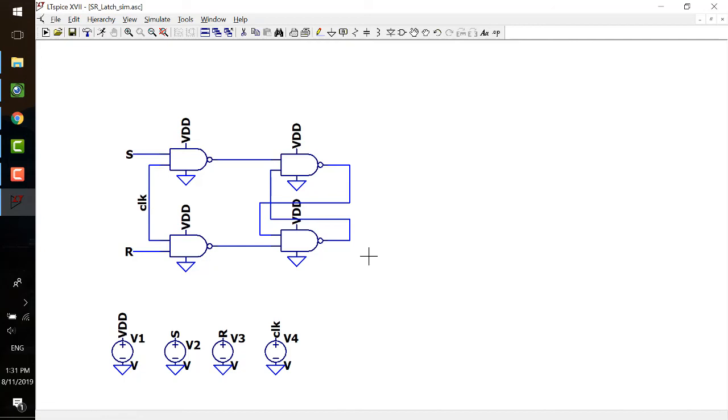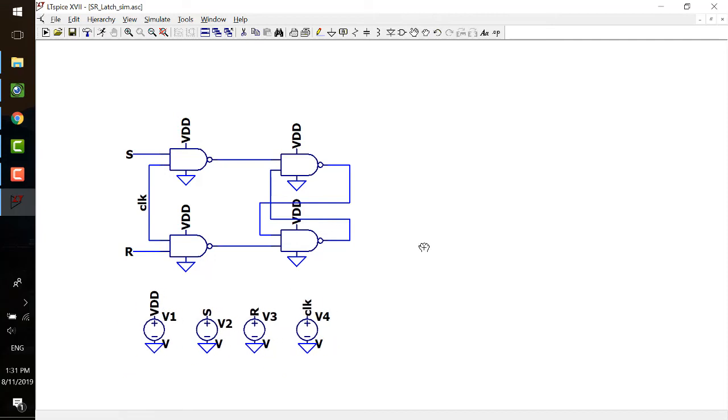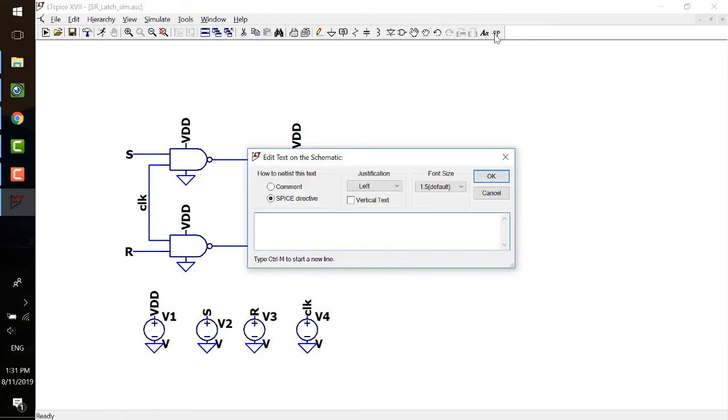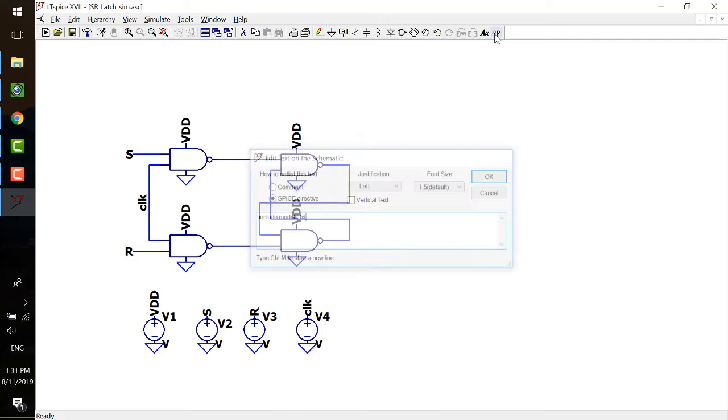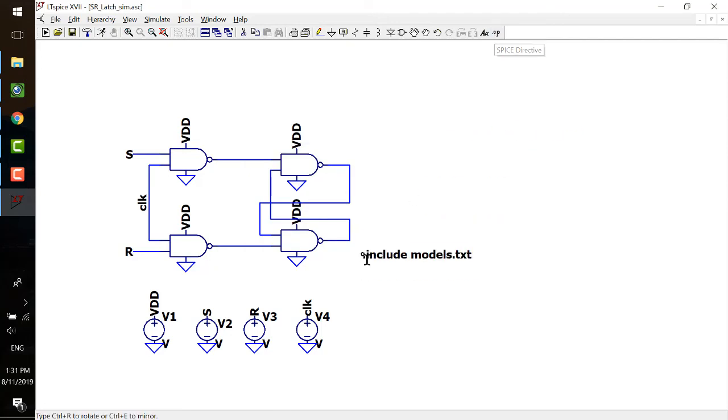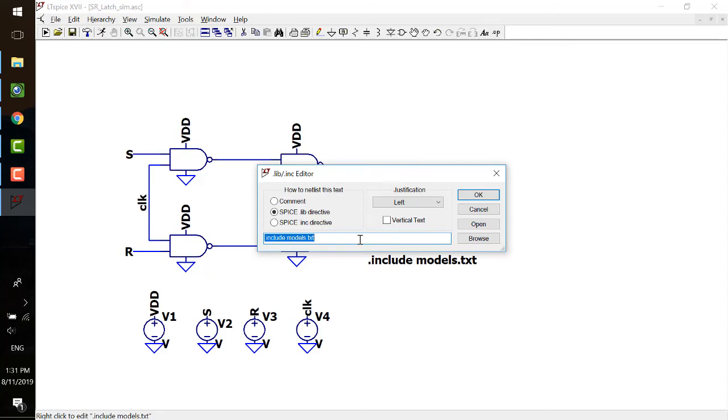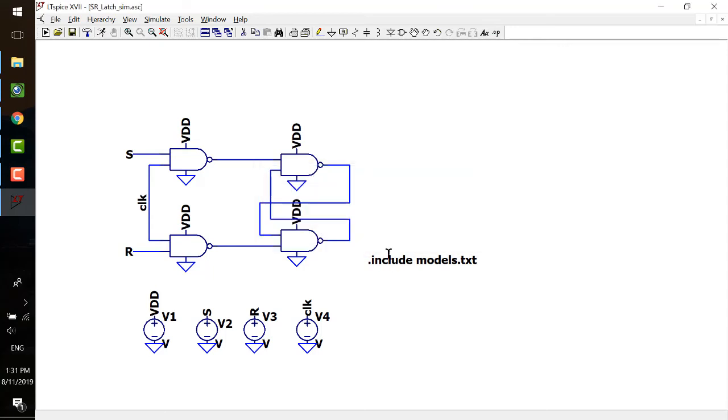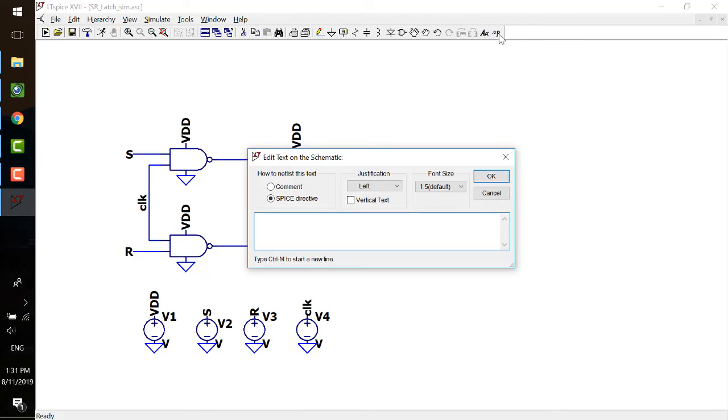So you have a clock signal. And now we have the circuit already built up here. So before we move forward, we need to go to .op and give a model file. Oh, before we do that, let's right click to fix it. Control, yeah, I'll delete it. Dot include, Control Enter. So you're not closing the window, but just shifting the line.